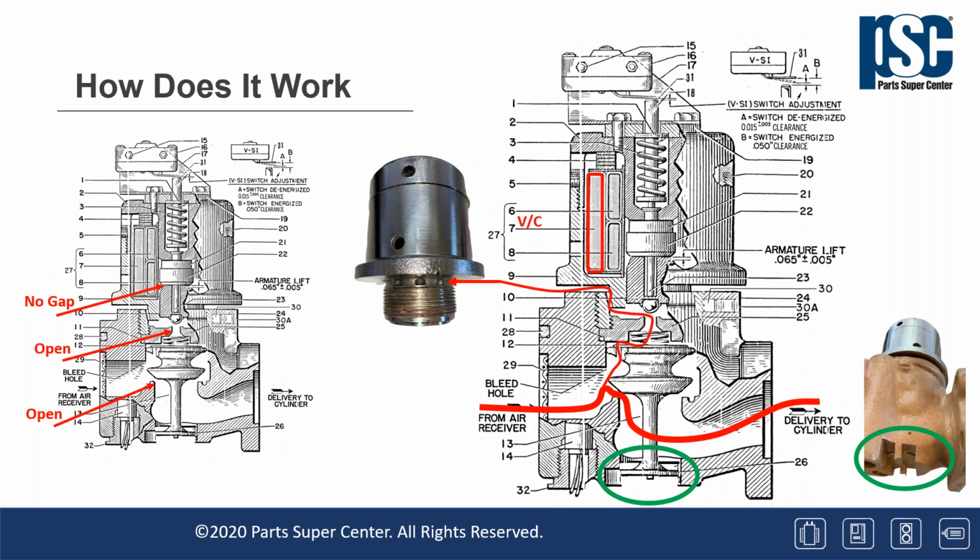The piston is now lifted due to the negative differential pressure above it, and the exhaust port's now sealed off. So air is being admitted directly through the control valve to the main cylinder of the circuit breaker in an attempt to close the circuit breaker. As the circuit breaker approaches the completed closing stroke, an auxiliary switch or mechanism auxiliary switch will interrupt the flow of current to that VC winding in that closed valve coil. Let's see what that looks like on the next slide.